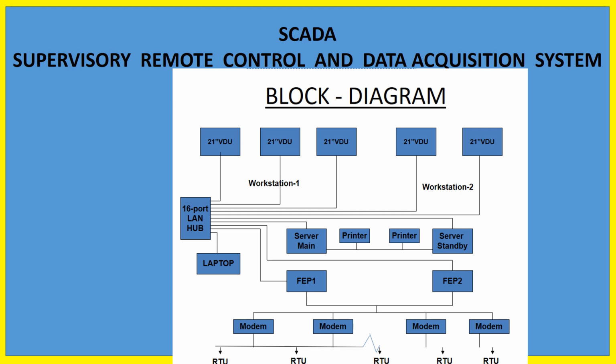Then the interrupter has contacts for open and for close. This contact will make after opening. So again a code will be generated in the field. This is called a remote terminal unit, RTU. This code is telesignal. Again it will be modulated.